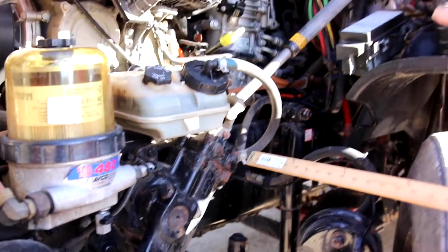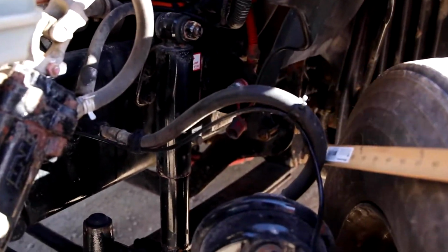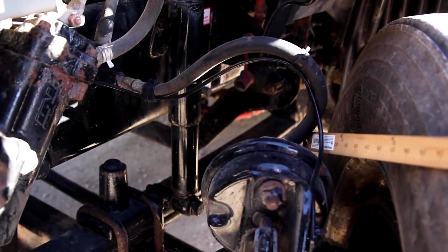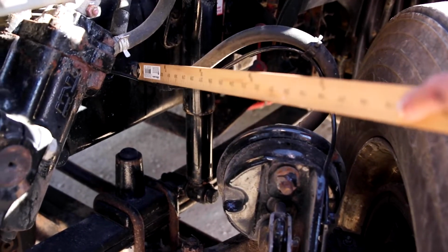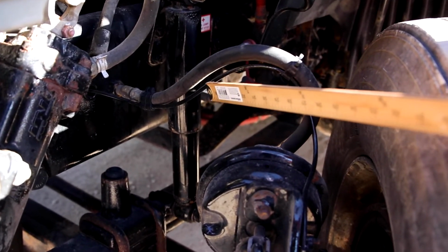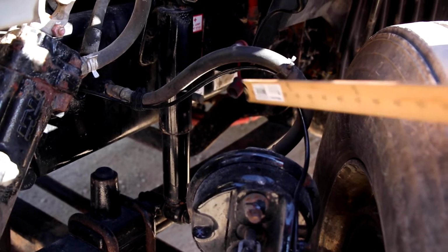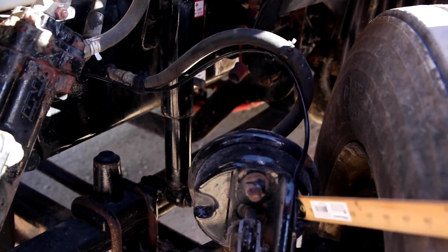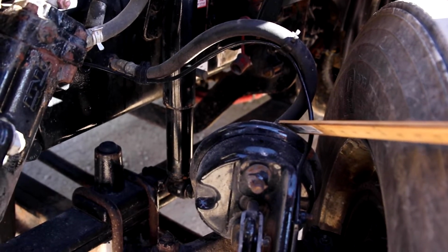Next, we're moving on to the brake system. This is your brake air hose that is connected to your brake chamber. It is air, so you want to listen for audible leaks. This small black wire, or it could be a different color, that is your ABS, or your anti-lock braking system wire that runs down to a wheel speed sensor. You want to make sure there are no exposed wires on that.